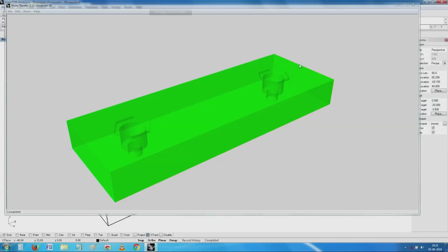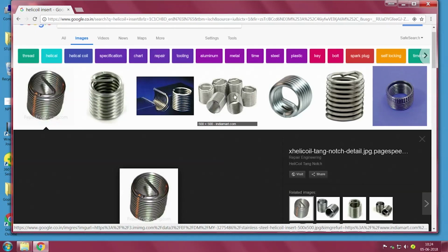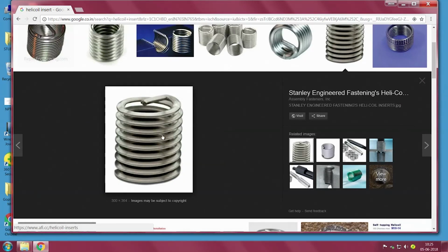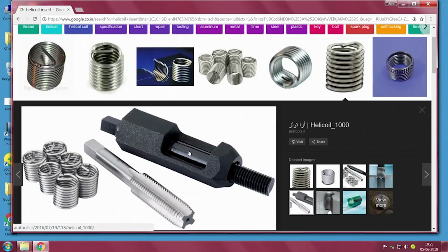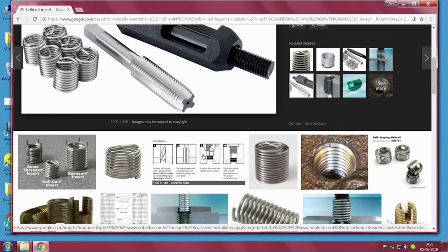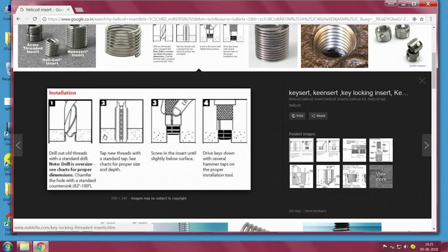I will just see if the internet is still working on the other monitor. You see, in the case of aluminum, it does not hold threads well, and even though you can tap it once, most aluminum alloys have a tendency to lose the threads after a little while. So, what is done is a helicoil is inserted into it. You have seen this? It is a coil which comes with its own tool, a tap set. You tap it to the next oversize, then you insert one of these. Well, it works well, but we still have a little problem when it comes to using it in plastic.